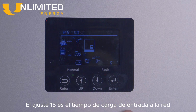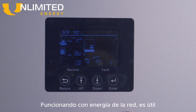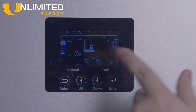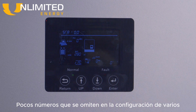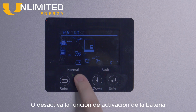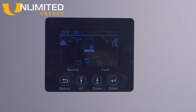Setting 15 is the grid input load time, where you can input set times to be running on grid power. It's useful if you want to take advantage of low-cost times, but don't want to use the extra power to charge batteries. There are a few numbers that are skipped in settings for various reasons, but we will move on to setting 17. This simply enables or disables the battery wake-up function that trickle charges low battery banks to pull them out of a protective sleep state.